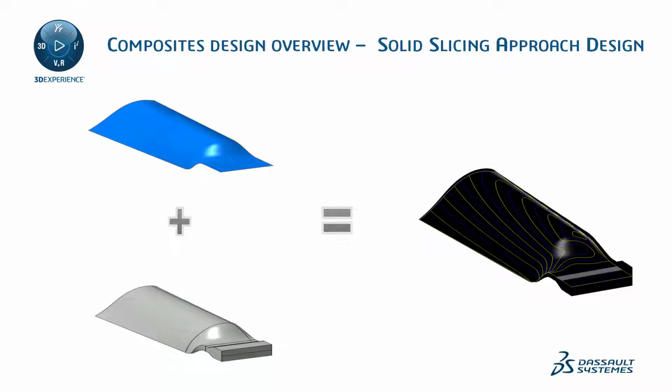Using this method, the user can slice the associated solid that is created using the zones for creating plies. This method consists of two sub-steps: slice the associated solid created from the zones to create the slicing curves, and create the plies using the slicing curves.